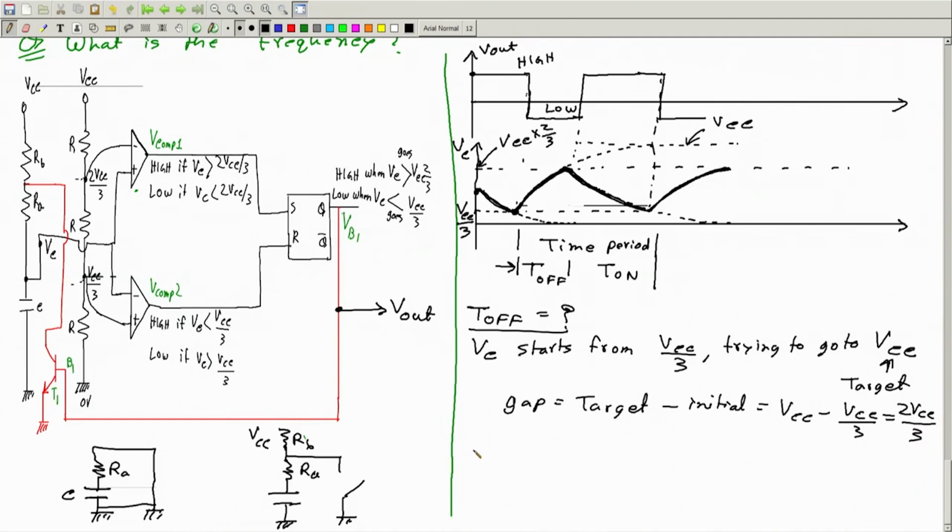And therefore the capacitor voltage VC you can write as target minus this. So what will happen? Finally, this term will be 0, so the final value will be the target value as t tends to infinity. Initially when t is 0, this is 1, so this part is not there. Then the target cancels, and we will have only the initial value. So this is how the capacitor voltage changes. Okay, so let's write it this way.